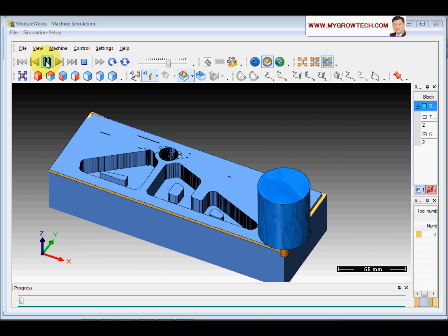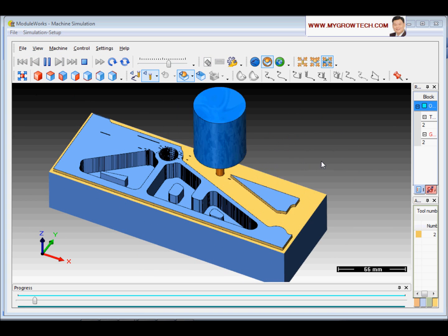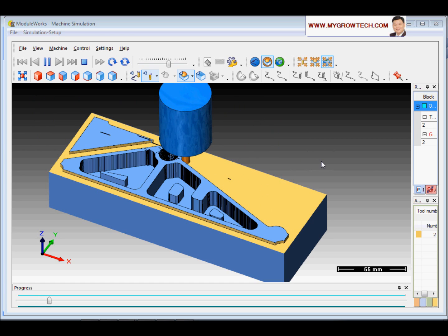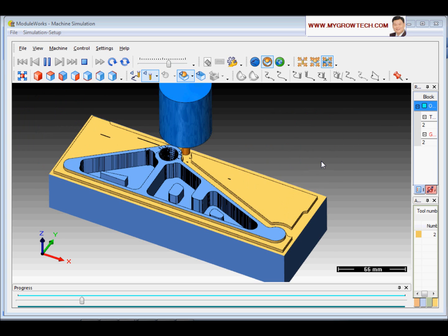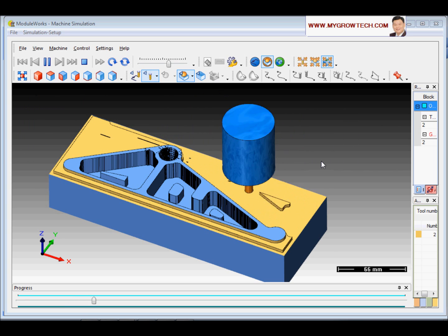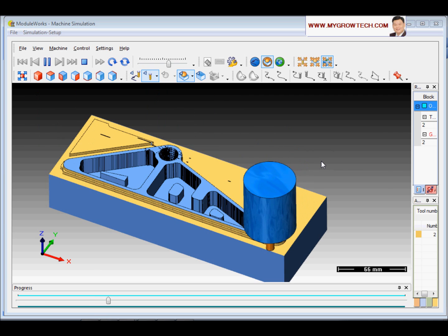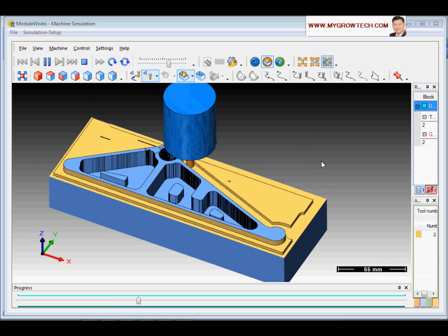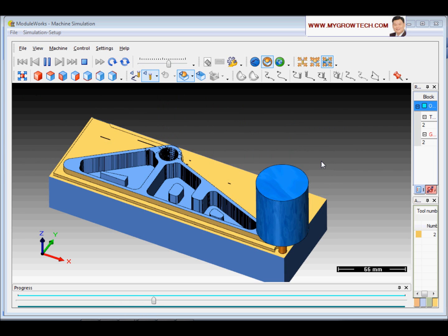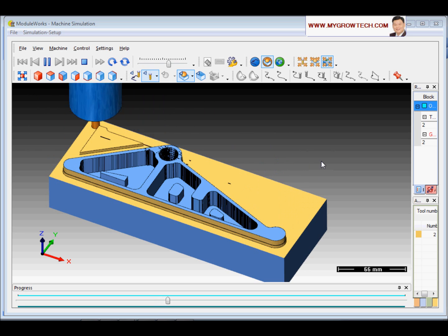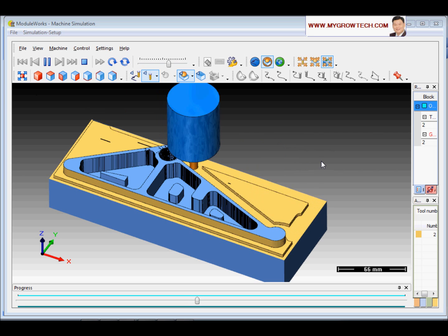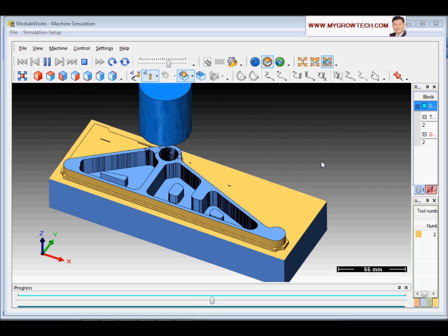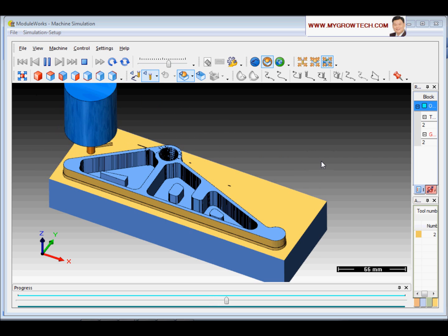And it will cut automatically outside in, because the best cutting method for cutting a punch is outside in. By using outside in, we will not have the internal corners. Although just now inside the motion parameters I set the spiral to be inside out, the result will be outside in if you select the outer contour as a stock contour. This is automatic.